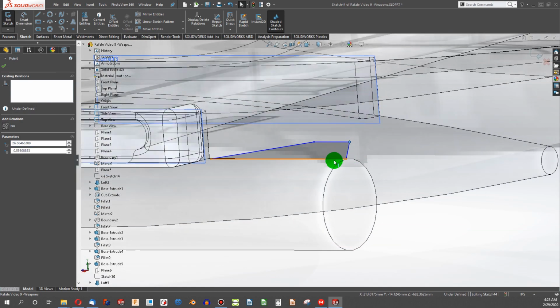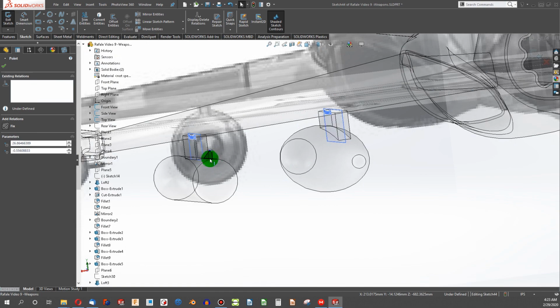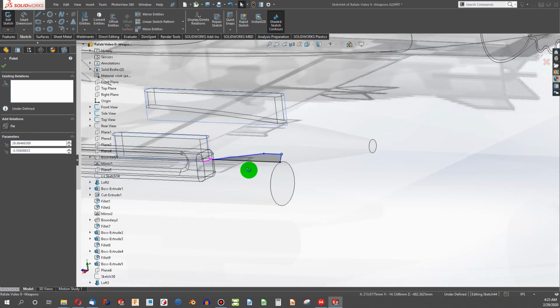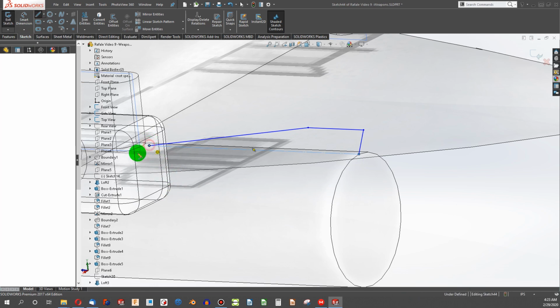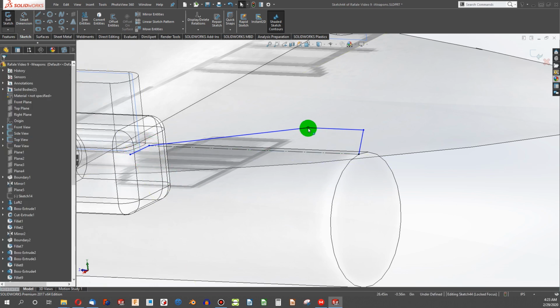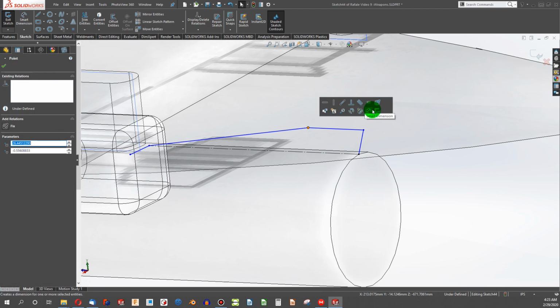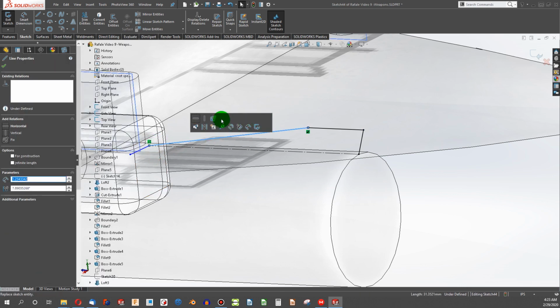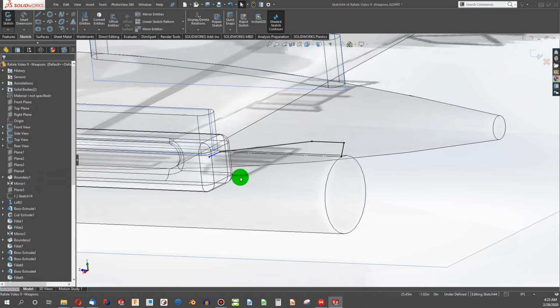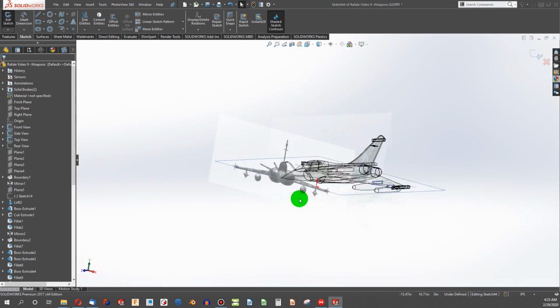The next thing, if I extrude this, you'll see we'll have a tangent point, and the fin will only touch the wing at one single tangent point. So to remedy that, we'll make this for construction. We'll continue this line here, and heck, I can even use fixed geometry if I like what I'm looking at, and that will simply speed us up where we're at. Again, I don't normally recommend using fixed geometry, but this is a different project than what I normally do.